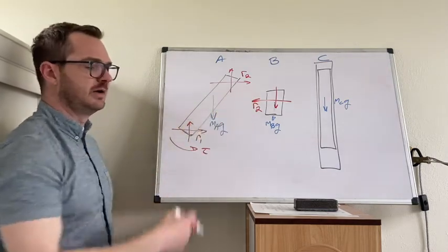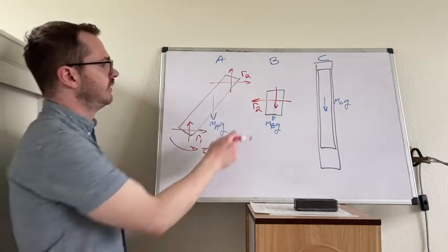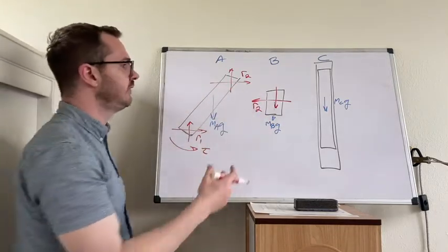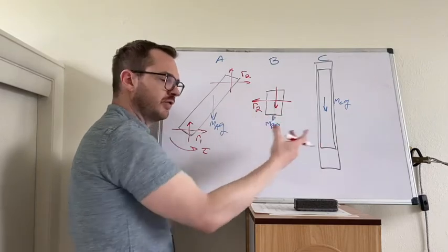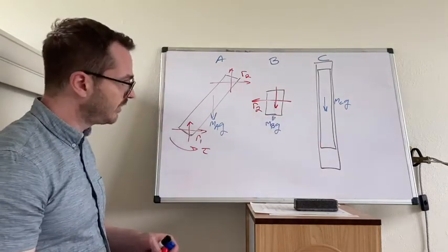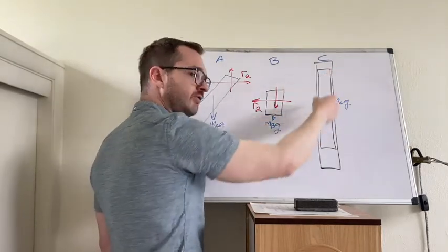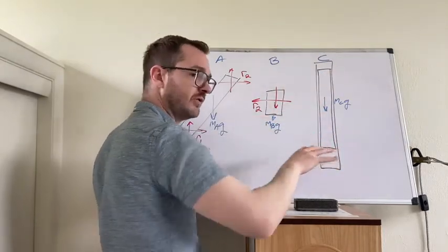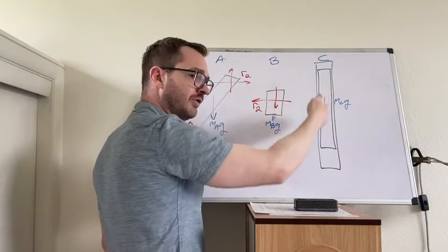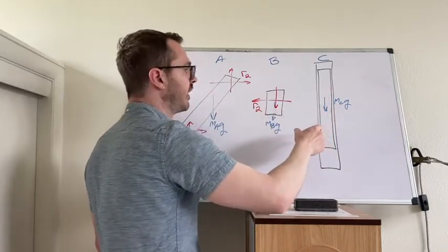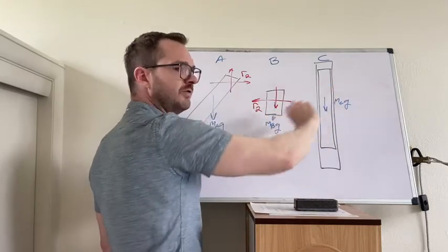This is action-reaction. So there's gravity, there's R2, there's also the joint between B and C, which is the groove. So let's think about that groove. It allows some motion. It allows the block to slide. So there is no restriction, there is no constraint in the groove direction. However, you can't take the block and arbitrarily move it left and right. Also, you can't arbitrarily spin it.